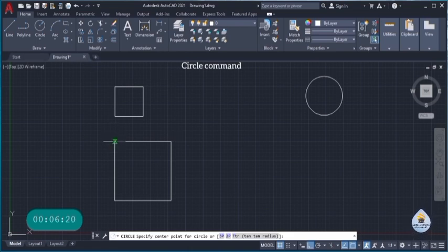Now you see that it snaps automatically to this point and says it is the end point. The reason it's doing that is because my object snap is on, right? This is our object snap here. Once it is on, whatever I want to do, my cursor will always snap, as if like a magnet, to any important part on my line, like the end point, the center, the midpoint, another end point, and so on and so forth, right?